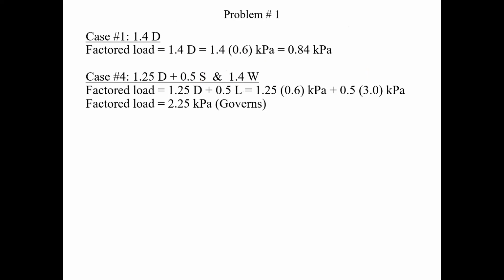Maybe I missed something, but isn't the wind load 1 kPa? 1 kPa, yeah. That's right. So here, all I'm doing right now is calculating the gravity loads. In other words, what is this 1.4 multiplied by 0.6? 1.4 multiplied by 1.0 kPa, kilonewtons per meter squared, times the tributary width, which will give me my WF.